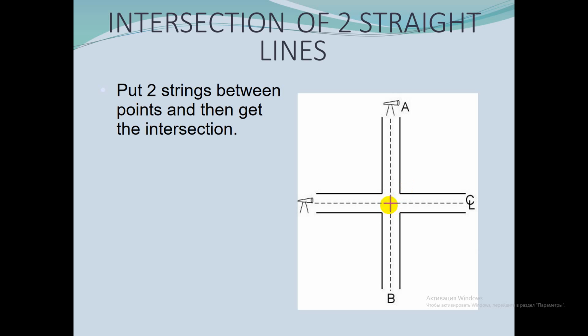With the instrument set on Main Street station and a sight taken also on the Main Street, two points are established on the Main Street, one on either side of where the surveyor estimates that the Second Avenue will intersect.